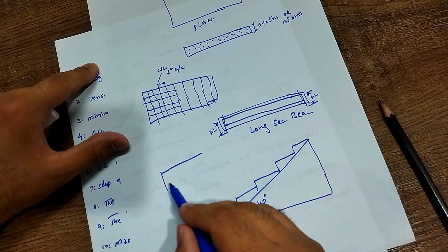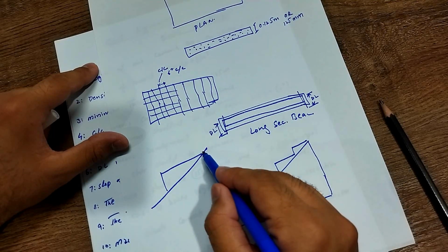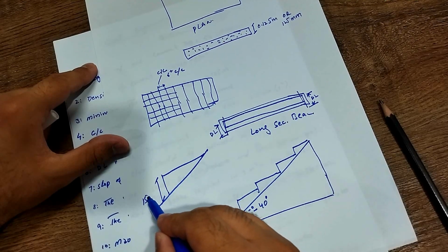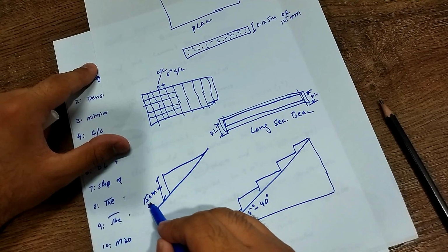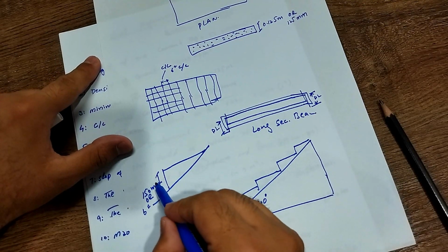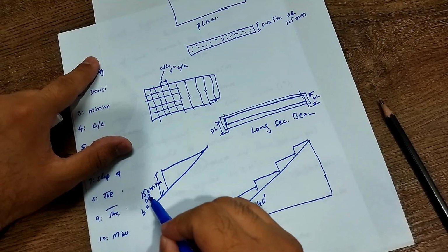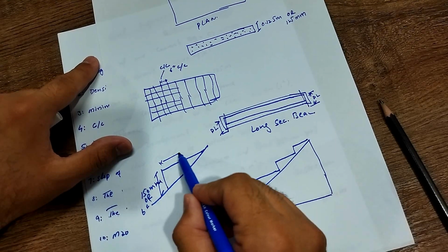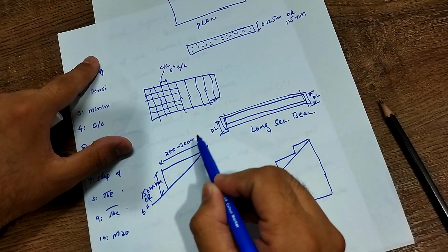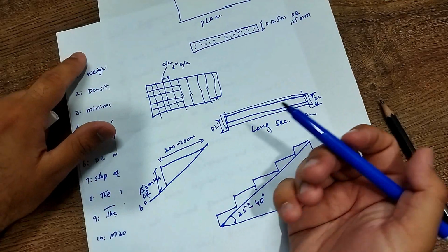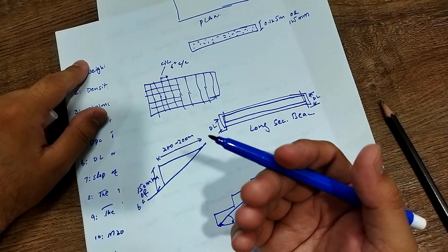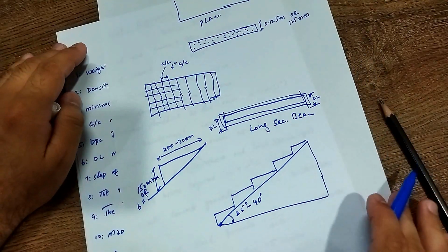This is the riser and this is the tread and this is the stair. Okay, this riser should be 150 mm or 6 inches. Okay, should not be greater than 6 inches, otherwise the people shall face more difficulties. And this is the tread. The tread should be 200 to 300 mm, 9 inch to 12 inch, and otherwise depends on the design and the traffic flow of people.